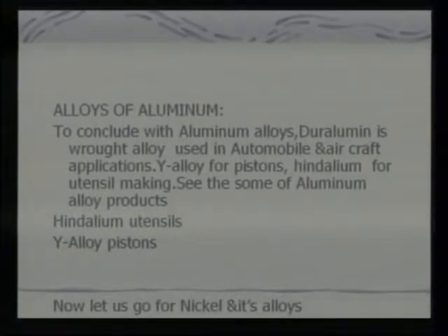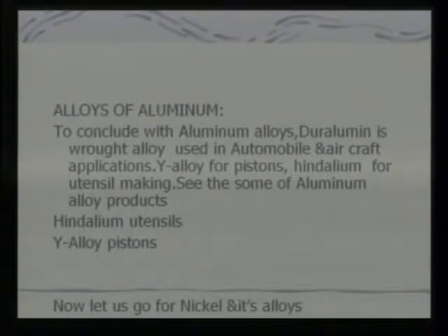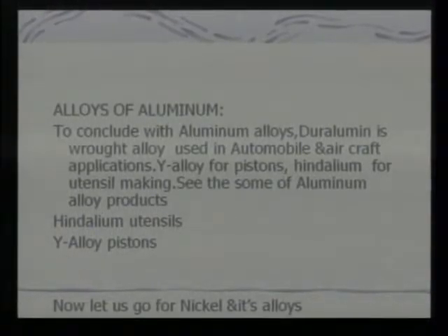Magnalium, with magnesium 2 to 10%, copper 1.75%, remaining is aluminium, is light in weight, possesses good mechanical properties, and is useful for aircraft and automobile components.